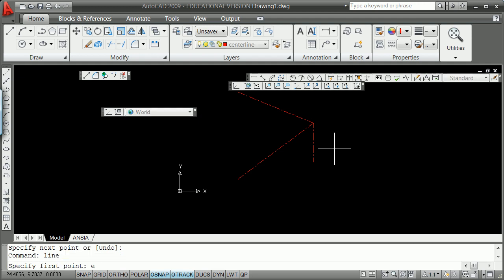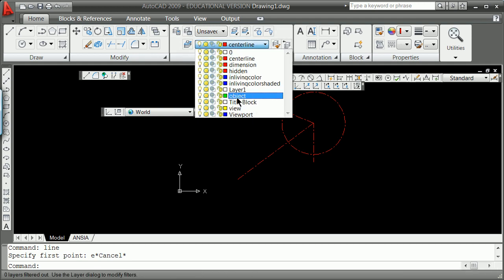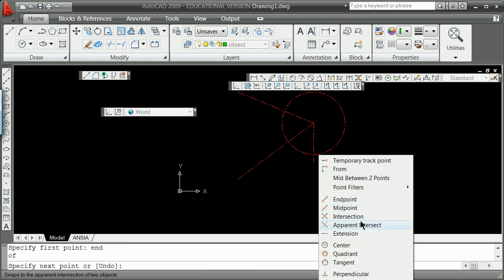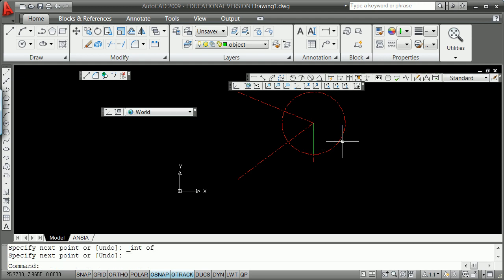So I'm going to go a line from the endpoint here. I guess better yet, get used to doing it this way. Circle from the endpoint there, radius of 5, and then you can basically do a line from right over the top if you want. There are all kinds of different ways. I don't really care how you draft this, but you do want to start to use layers so your brain makes sense of things to the intersection. So you start to break your rules there.